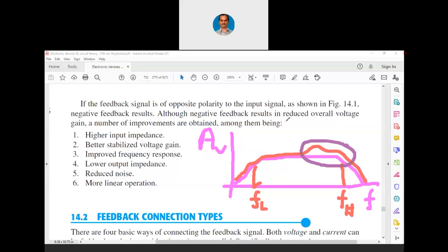All types of junction capacitances, transition capacitances, they are all coming into picture. So in such a case, at very high frequencies, the device's internal parasitic capacitances may introduce some other response, due to which the gain may be affected. At some frequencies, the gain may go to higher range and it may come down. The reverse is also possible. That means the gain may come down at a particular frequency range.